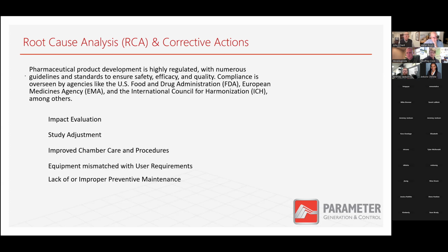There's a follow-up one. What is the industry standard amount of time for the chamber to be out of spec where there is no impact to the studies? And that's an interesting one because officially, for a commercial product, you could be out as long as 24 hours. I've always had a bone to pick with that particular one because there's a difference between being off by a few degrees from room temperature for 24 hours and being off of 40/75 for 24 hours, a major impact.